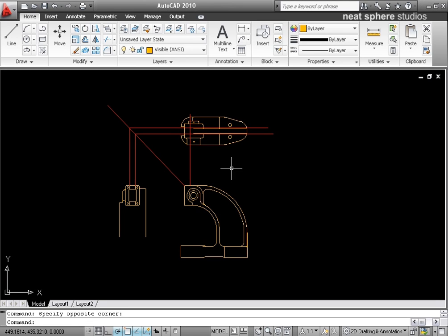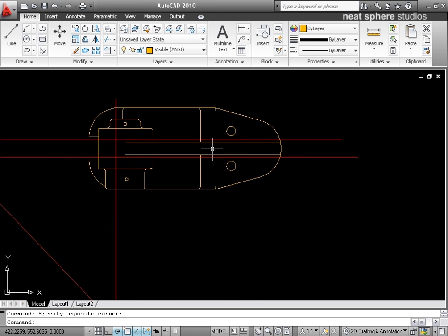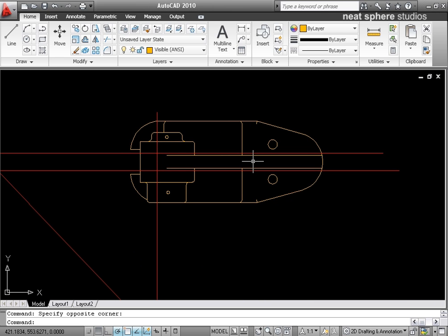Often when working with drawings, what we might do is create construction lines. These construction lines really just help us to place objects and elements within our scene. With a drawing board, we'd be setting up a parallel rule and making marks on the page. What we can do with the computer is put whole lines in, and then just delete them as and how we want.